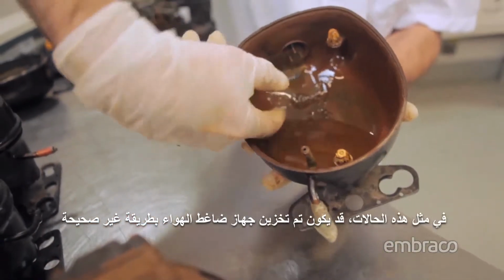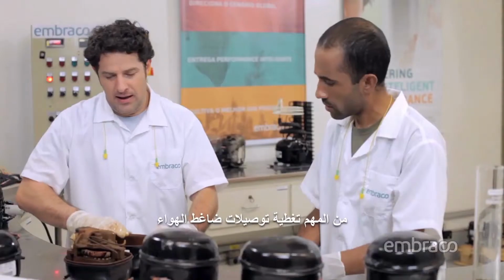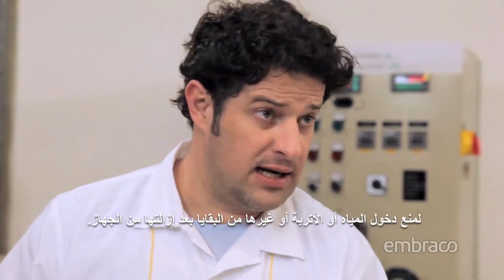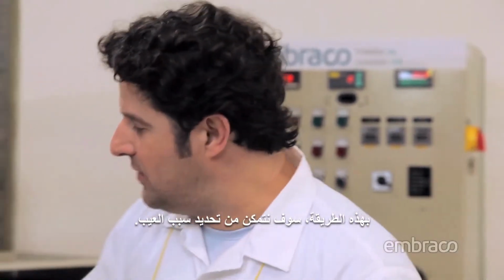In cases like this, the compressor might have been improperly stored before its shipment to Embraco. It's important to cover the compressor's connections to prevent the entry of water, dust, or other debris after being removed from the system. In this way, we will be able to actually identify the cause of the defect.